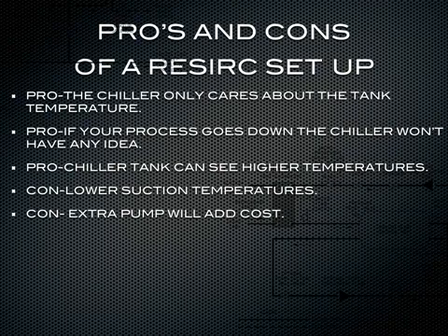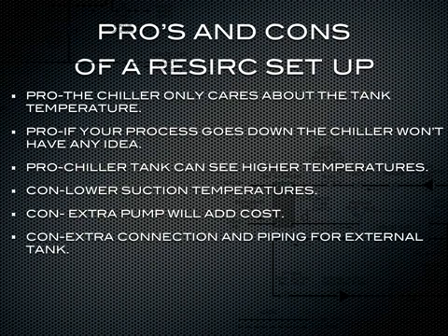Another con is you're going to need an extra pump, and that will add cost. And another con is there's going to need to be an extra connection and piping for an external tank. So on a once-through, there's going to be an in and out. On a recirc, there's going to be 2 ins and 2 outs because you're creating 2 separate loops.